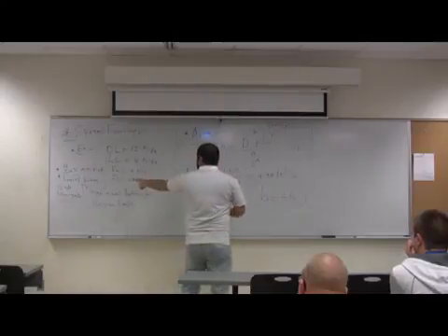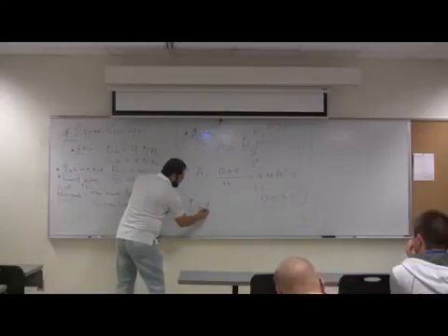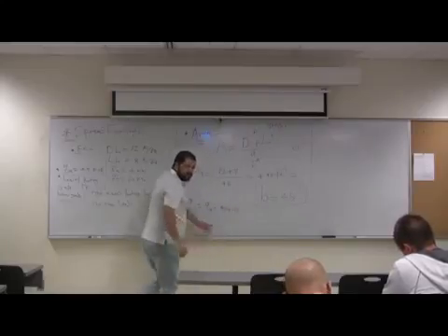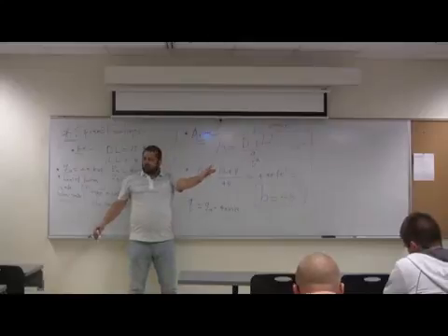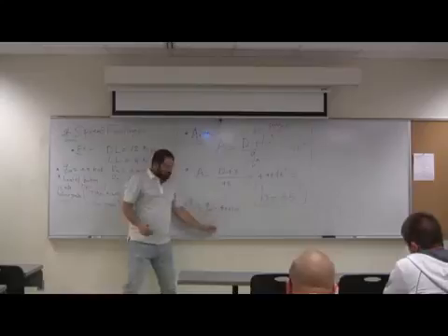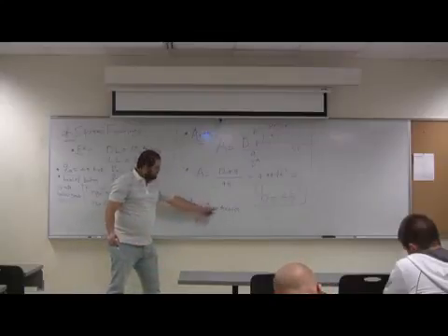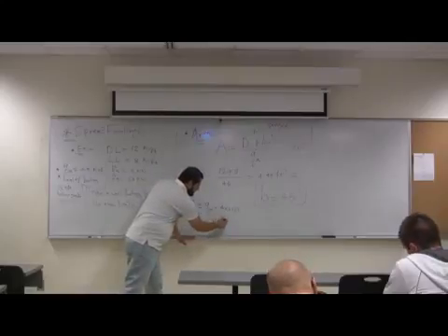So now, this Q equals Q allowable minus 4 times 0.125 if you want to do it this way, or you can do 1 times 0.15 plus 3 times 0.11 if you want to take it as 110. But this is usually common practice. How much do you get? 4.5 minus this number. Q equals 4 exactly. 4 kip per square foot, or KSF.